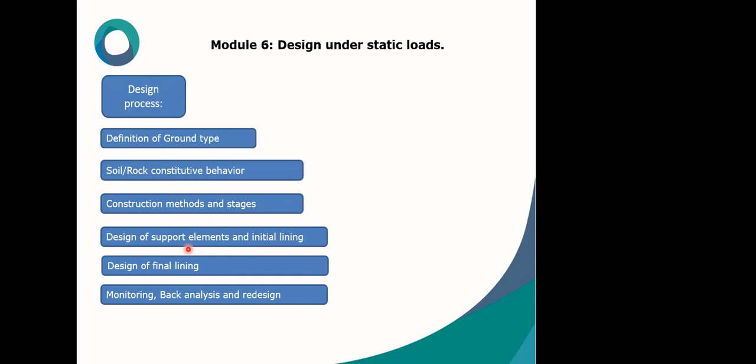In this part, we are going to talk about the design and construction material properties in detail. For example, in the absence of precise calculation, beam stiffness could be assumed to be 50% of the uncracked section of the mentioned beam in restraint frames, due to the ACI.